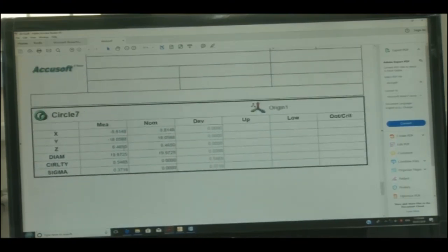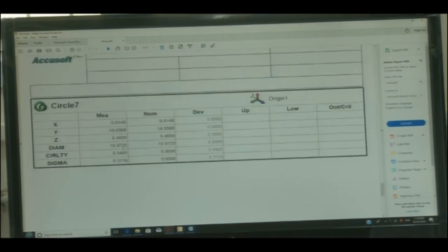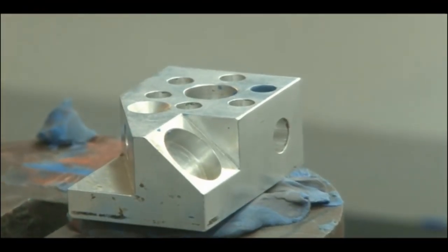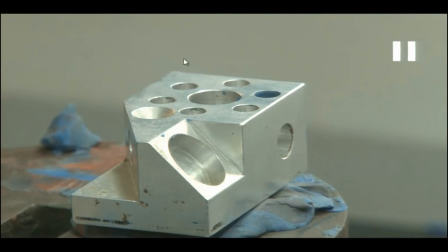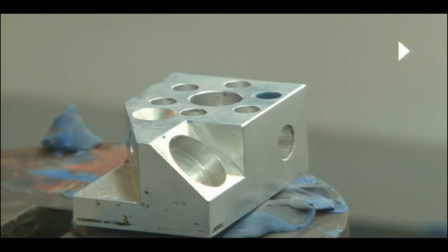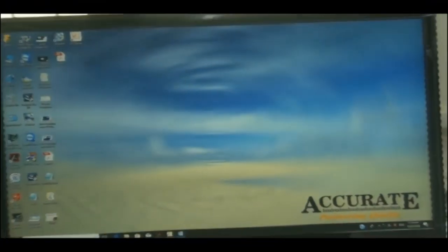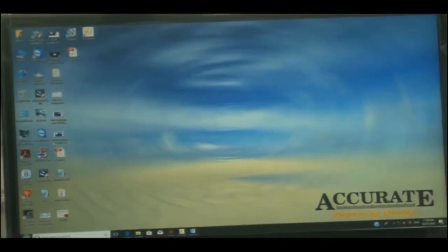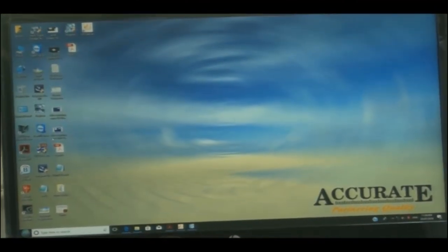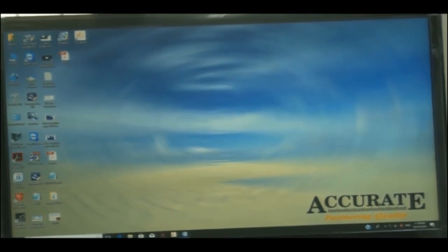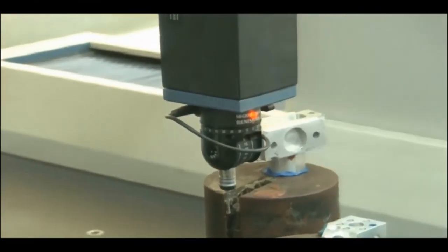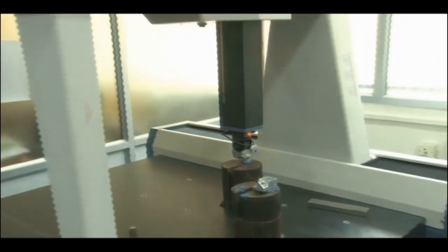Not only this data, the coordinates, we can also generate the equations out of them. Also we can obtain this same 3-dimensional feature, this shape. Like I said, from this point cloud I can generate it, because this was a structured form. So, I just used the manual operation. I can also use the CNC operation. In CNC operation, what we do is we put the joystick away. We wouldn't use the joystick, and will command the machine that at each 1 mm or at each 2 mm it will locate the points.